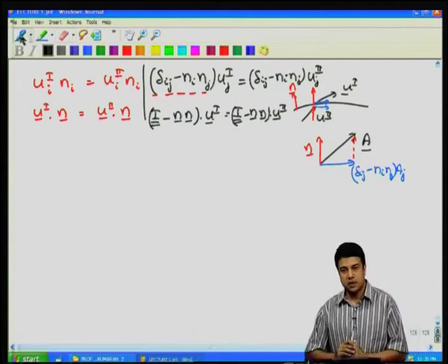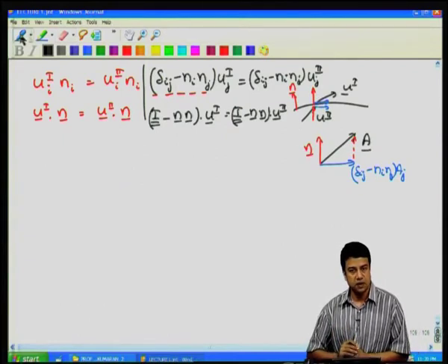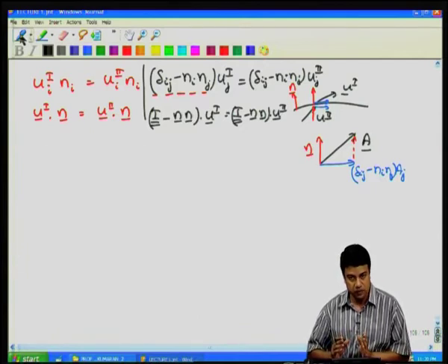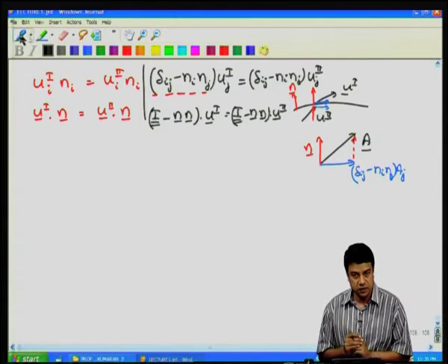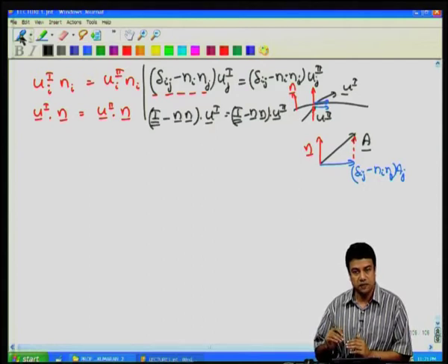The other boundary condition that you need is the continuity of stress at the surface, that is, the force per unit area, both normal and tangential to the surface, has to be equal on both sides. The tangential stresses have to be equal, because you cannot have a net force exerted by the interface itself. However, you can have a net force normal to the surface exerted by the interface, that is the force of surface tension. So, the surface tension force acts normal to the surface.